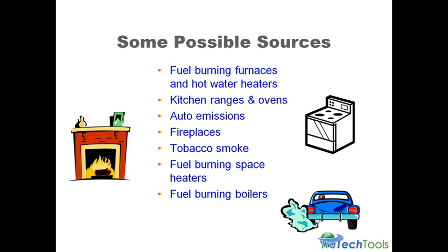We had a customer one time, we're testing the furnace, and all of a sudden the CO level in the burner starts to rise, and we're looking for problems with combustion air. We're thinking, well, we must be starving the appliance for combustion air, something else is going on. We're checking the fuel regulator to see if we're overfeeding gas, can't find anything. Well, the customer had started their car in their garage, and CO was coming through the sill plate from the garage into the basement, getting picked up in the combustion air, going right through the combustion process and raising the stack level CO. And I'm sitting there thinking it's a furnace problem, and it was an auto problem. So, that can happen.